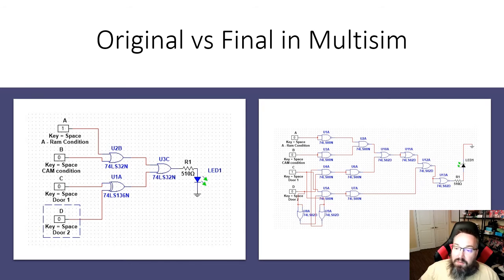So I started off originally with NAND gates, and then once I ran out of NAND gates, switched over to NOR gates since both are universal gates and both can be configured to all the other gates. I still kept the same output configuration and once again tested my final circuit in Multisim to make sure that the truth table still held true.